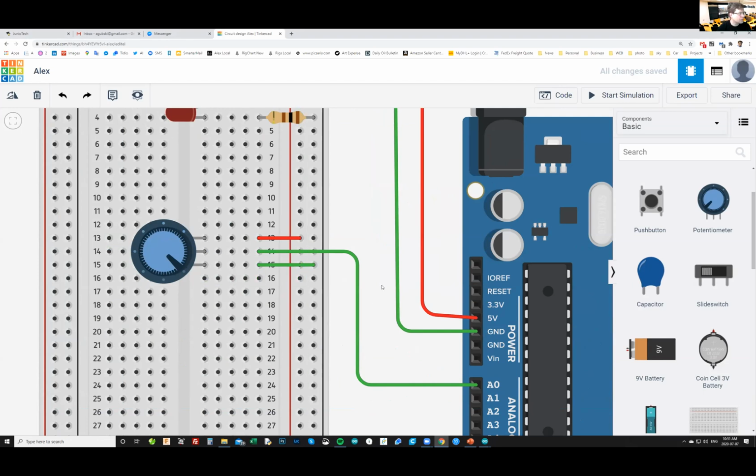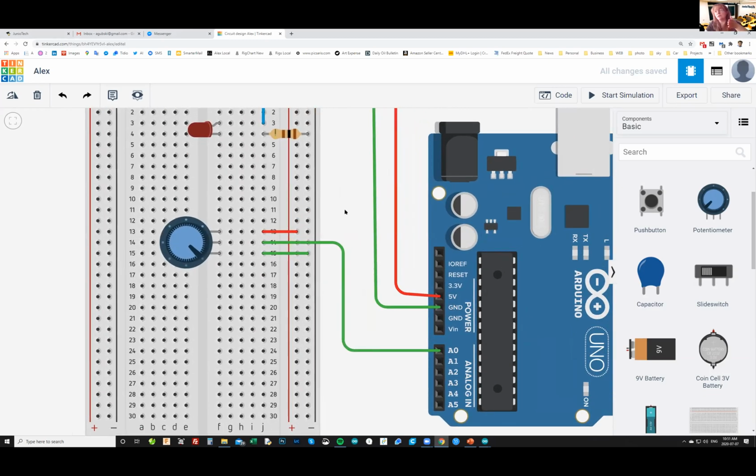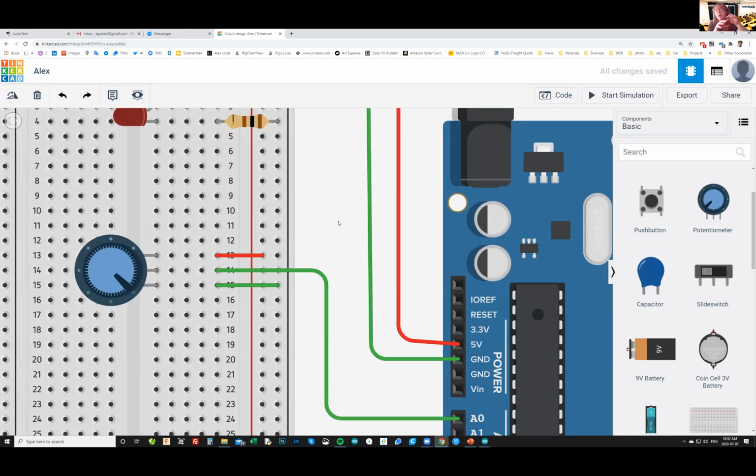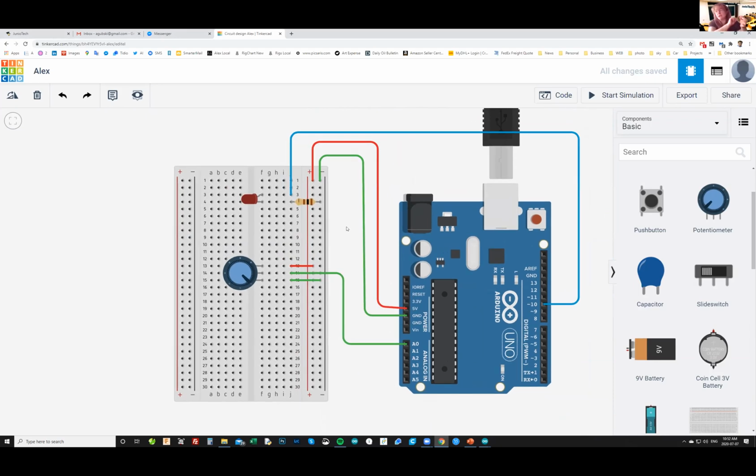Guys, remember, electricity on your breadboard doesn't flow through the gaps. So if anything happens on the other side and it has a gap in between, you need an extra wire to actually bring the electricity across that gap, okay? So guys, please remember, for you, it will be connecting like this. Yeah, just show it like that, because that's exactly what they have. Just keep it like that too. It's easier.